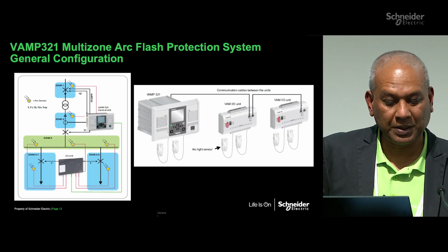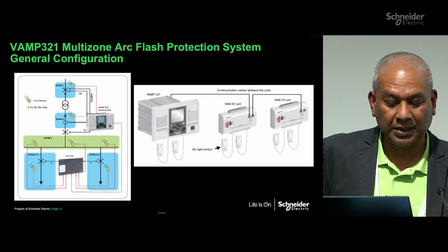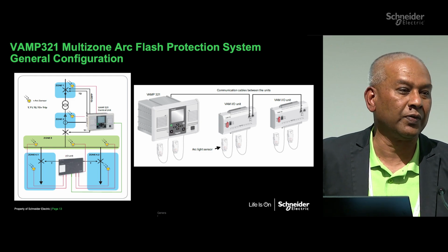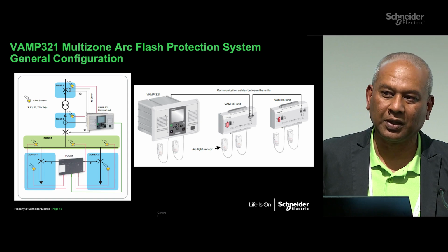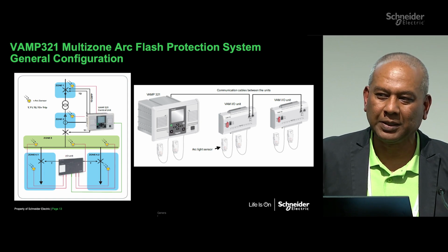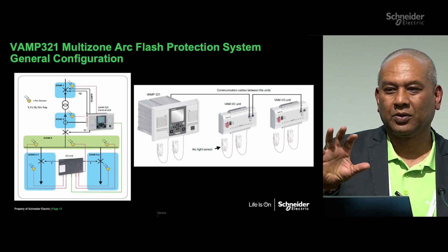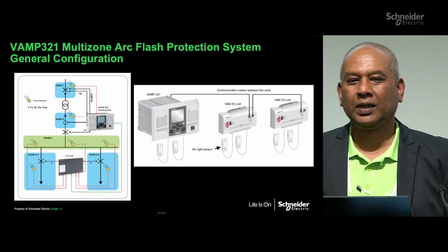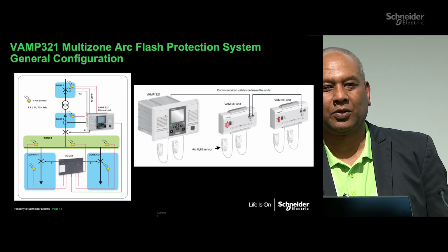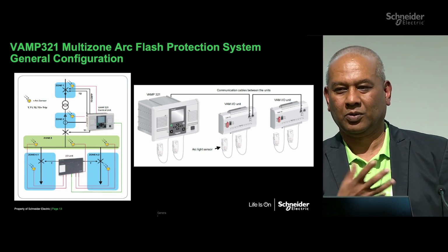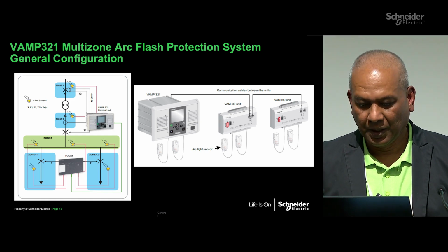One relay covering multiple zones. Each of those areas you see marked in green and blue are different zones and different tripping schemes for arc flashes and arc faults in those areas. So you don't need multiple relays to do that. You can do it within one relay by configuring. This is all set up in the configuration of the relay, which can be done outside, prior to going to site. So you do a relay config file, check it, and then send it to site for implementation.